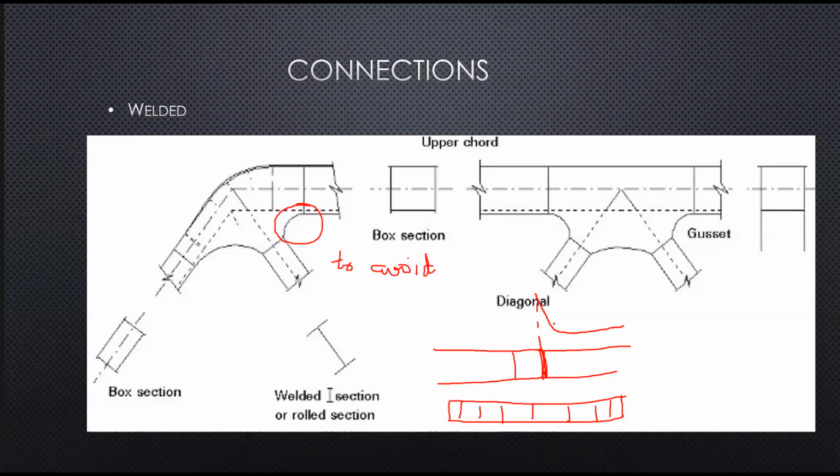This will actually enhance the stresses at that point. So in order to avoid that, we give a smooth joint, because fatigue is all about the difference between the stress. Fatigue is nothing but cyclic application of stress. So what we are really worried about is the delta sigma, the variation of stress.